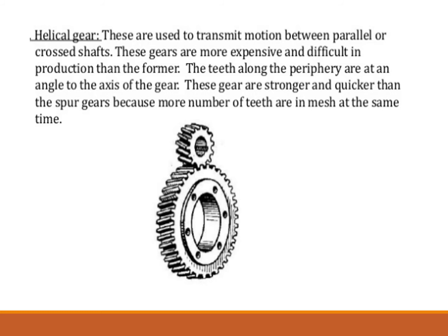However, in helical gears the friction, heat generated and wear are high because of the sliding action of one tooth on another. Therefore, helical gears should run in an oil bath, as in automobile transmissions. Another disadvantage with helical gearing is that helical gears exert an end thrust which must be absorbed by a thrust bearing.